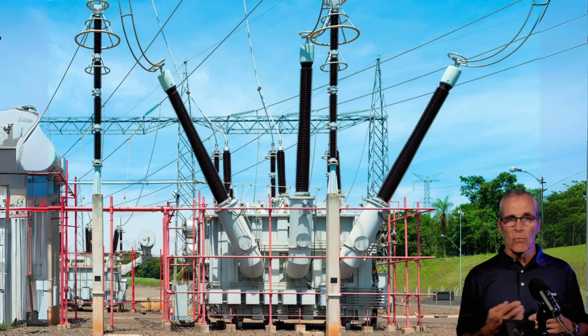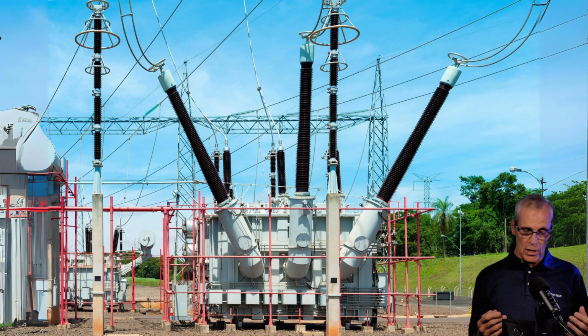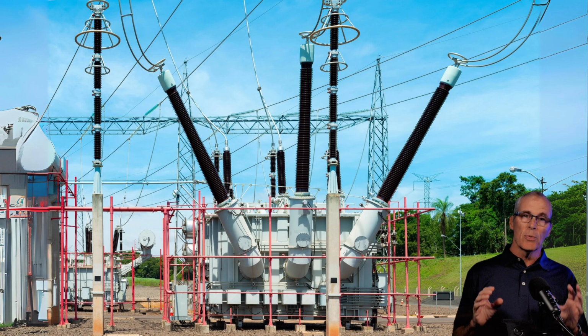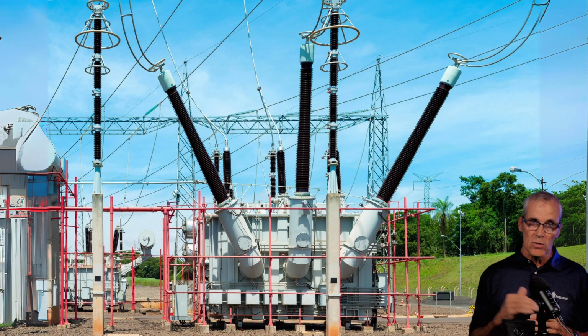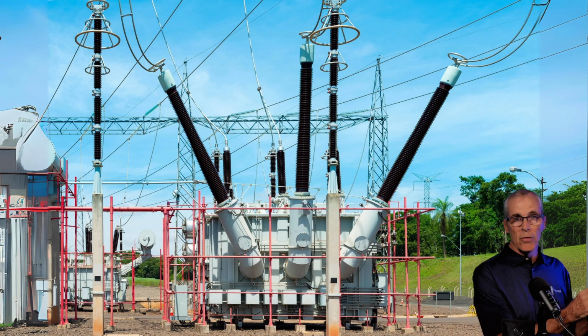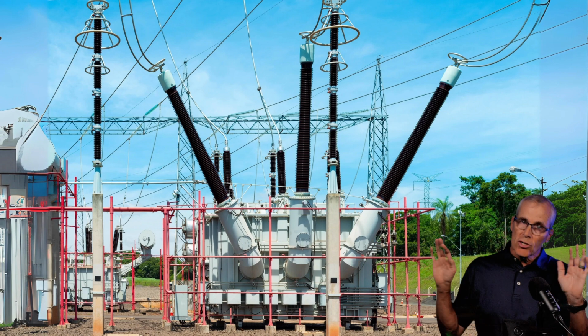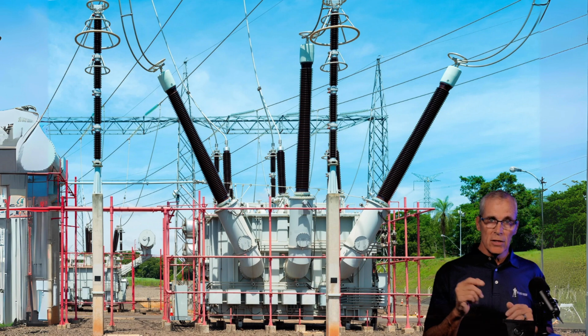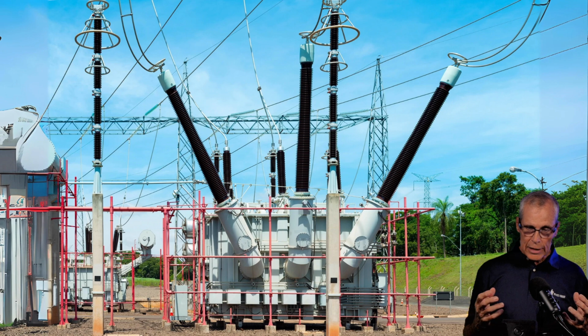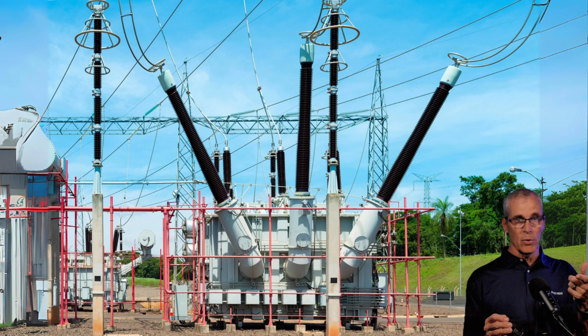Here's an example of where some big transformers are protected with water spray systems. A lot of people have the misunderstanding that water spray is there to put a fire out when that transformer fails. That's wrong. That water spray system is there in case another transformer catches on fire and the radiant heat from the other transformer is shining or exposing this transformer. So this water spray system that you see here is to keep it cool when another one has failed. It's not to put the fire out in this one.